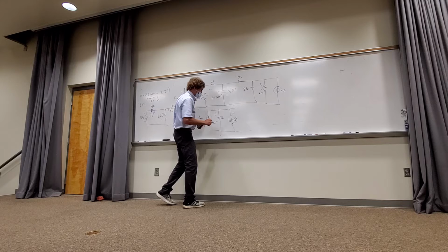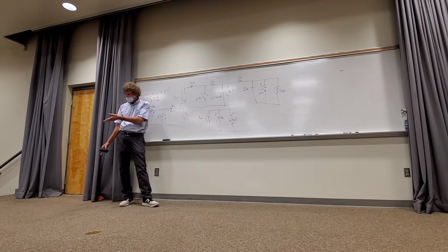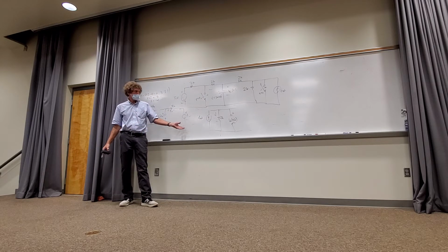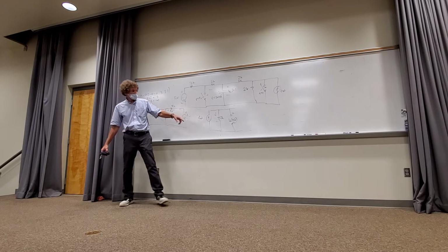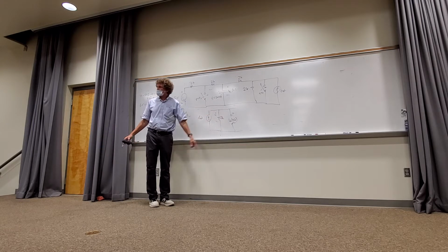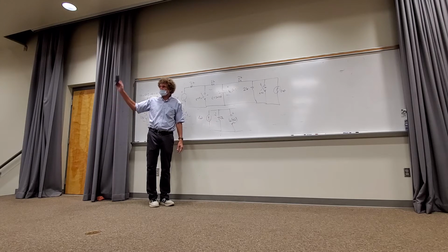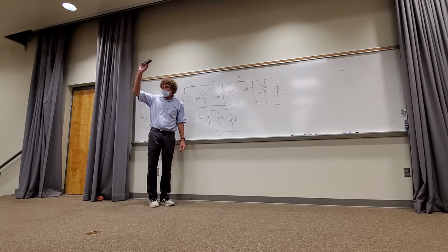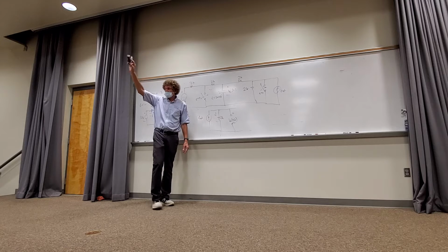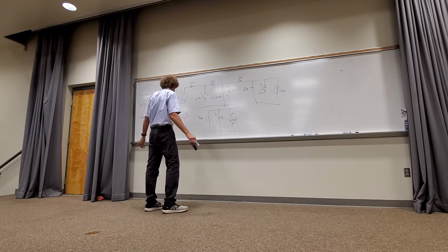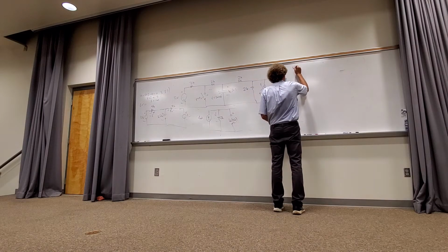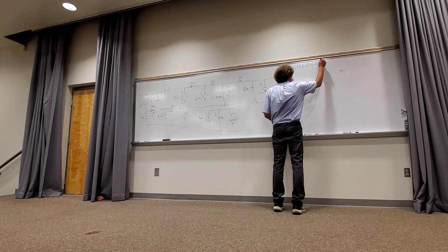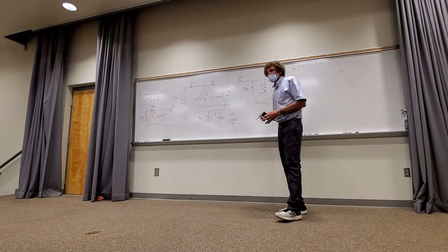So what's the voltage across the 2K? 4 milliamps times 2K is 8 volts, right? Y'all see the voltage across this, the voltage across the capacitor, where the capacitor was. How many see that? In the back there, y'all see it, class? Sure. So you get 8 volts no matter what is the point. So VC for t less than or equal to 0 is 8 volts. Good, check that box, right?